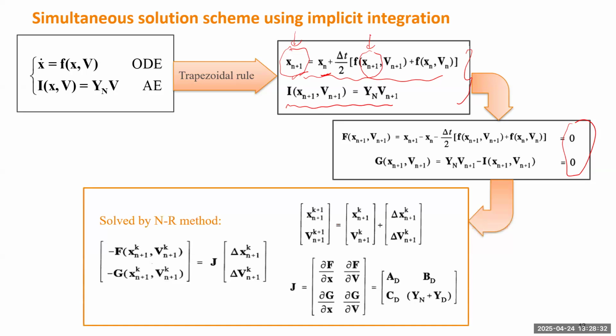At each time step, you need to solve this equation, similar to solving the power flow equation. When solving this equation, you need to take some iterations. You can start from 1, 2, until maybe a large enough iteration, until the n plus 1 state vector or the voltage doesn't update.